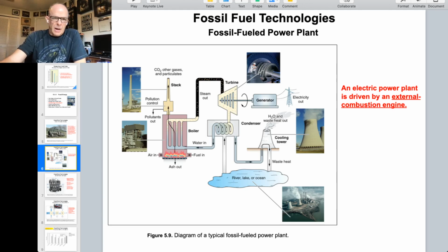The steam that passes by the turbine comes out with less energy. It's given a lot of its energy to the turbine, as we've learned from the law of thermodynamics. It can't give 100% of its energy to that because a lot of that thermal energy in the steam is incoherent. It's the random motions of the molecules of water. And so the steam that passes by on the other side is still warm, and we have to cool it off before we dump it into the environment.